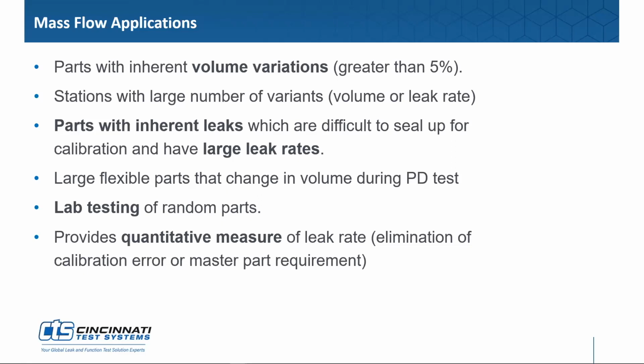And then also, mass flow testing works really well in a lab environment because when you're using a mass flow sensor calibrated for its own internal flow measurements, you don't have to have a part to calibrate to. So it works really well in testing random parts and random sizes. I always tell customers, if you've got applications where you're testing cats and dogs all day long, then mass flow is the technology for you. Yeah, absolutely. And then having the right range flow meter for all those cats and dogs is also important too.